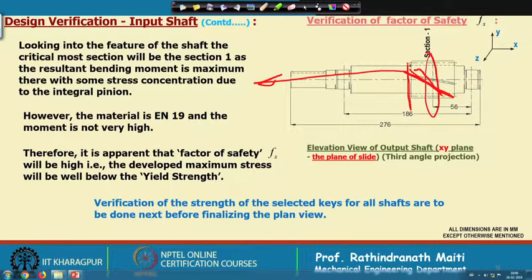Of course, it can be used also, but from the inventory point of view it is better to have two same bearings in a shaft, and instead of 6306 even we can go for 6205, that means 25 millimeter diameter, and as already discussed we can make this shaft input end instead of 25 millimeter, 22 millimeter.